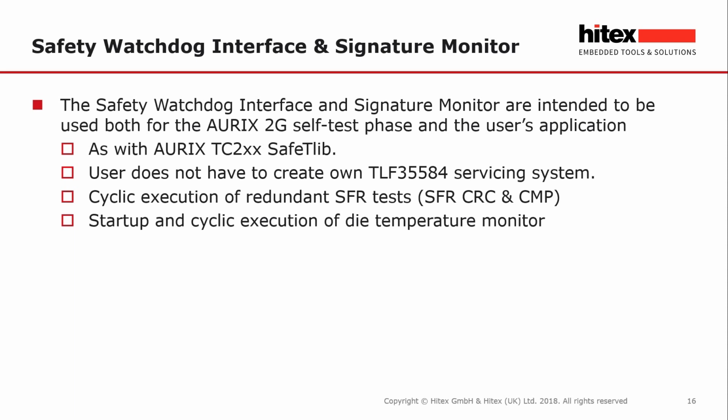Okay, the safety watchdog and safety monitor are intended to be used throughout the running of the process. So this is from the startup phase through the running phase when the user's application is actually executing. So the big advantage here is that you don't have to create your own TLF 35584 servicing system, and you don't have to provide a framework for the cyclic execution of the redundant SFR tests. All of this basically is taken care of by the SafeTpack.